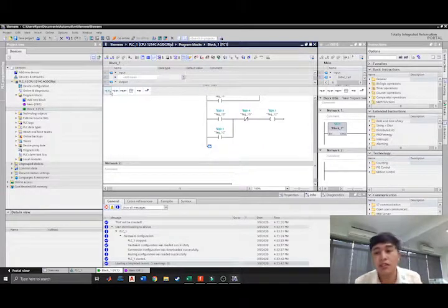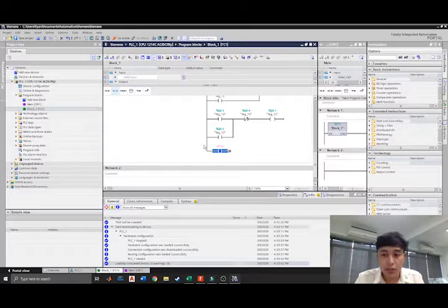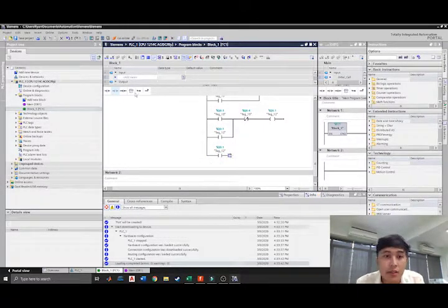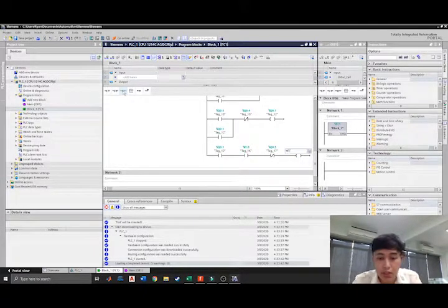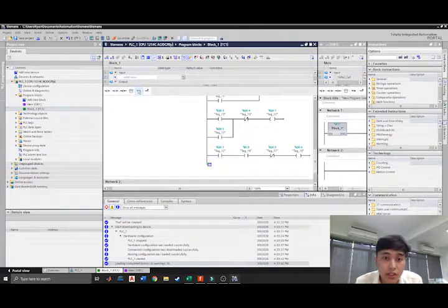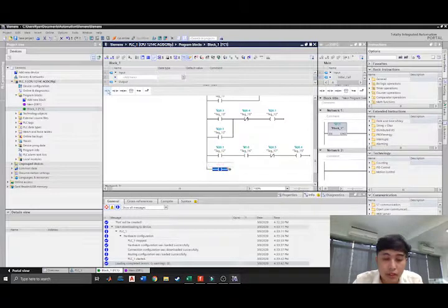And let's start with the opening condition, which is the last part, the supply cylinder retraction with the address of Q0.1, and also the reed switch that verifies that the supply cylinder is retracted with the address of I1.0, and then a normally closed contact of Q0.5, and then the output Q0.4, which is the transfer cylinder, and then a latch, Q0.4.